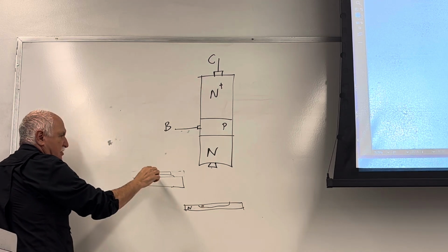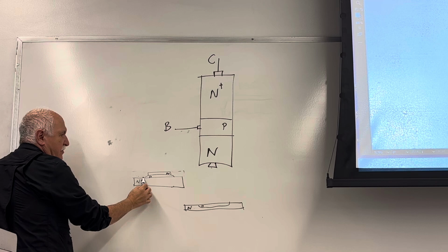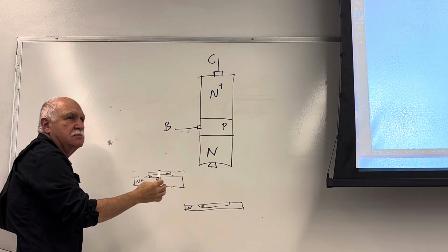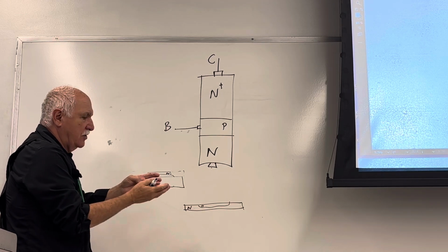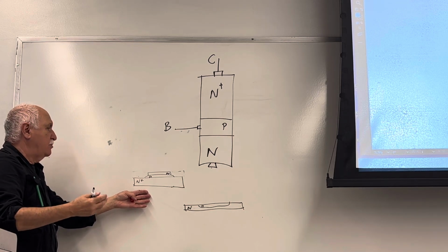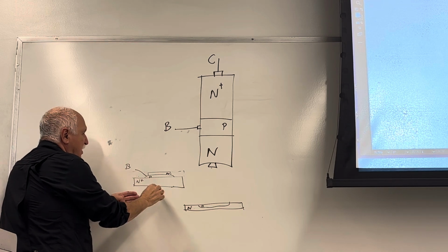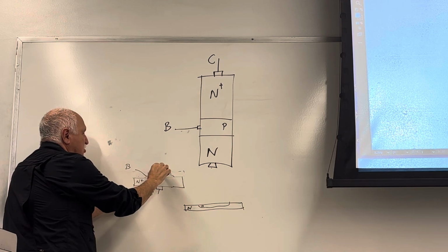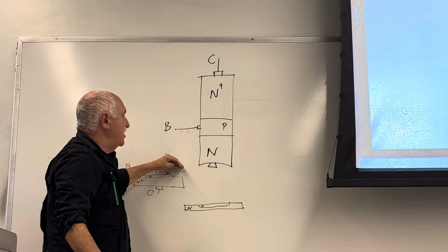Now that makes sense. So this is n, p layer, and then we have another n plus layer, heavier n. Simply, you bombard it with a higher concentration of phosphorus, and it becomes n plus. Then one becomes the base, one becomes the collector, and one turns into the emitter, creating those layers.